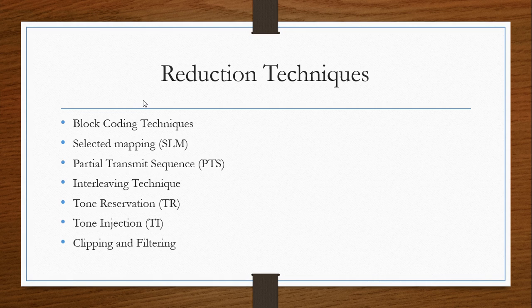The technique of iterative clipping and filtering reduces PAPR without spectrum expansion. However, the iterative process takes a long time and increases the computational complexity of an OFDM transmitter. Without performing interpolation before clipping, it causes out-of-band problems. To avoid this, the signal should be clipped after interpolation.